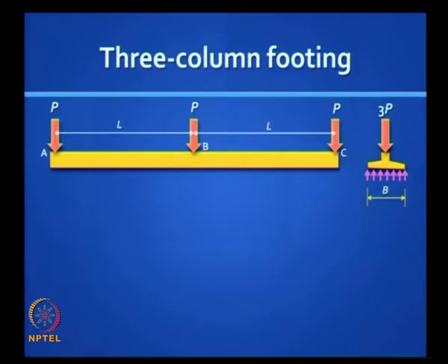Okay, you have a slab which you can treat like a beam, and let's say there are 3 columns, and let's say it's a symmetric system where you have 3 identical column loads P, P, P, and the spans are equal L and L, and you have a pressure acting from below, right? That's the soil pressure, and that soil pressure must be within the safe bearing capacity, and the settlements must be acceptably low. So longitudinally,